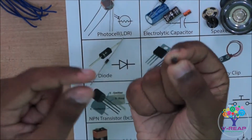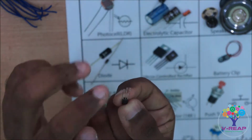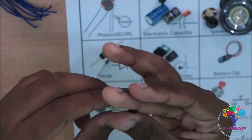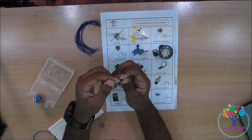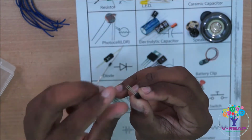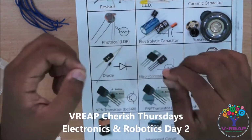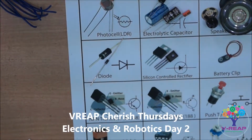The NPN transistor has a characteristic bend on the sides. The side two terminals have a slight bend in them. So let's place the NPN transistor in its place. Coming to the PNP transistor, it has 188 printed on it, and it doesn't have any bends on any of its 3 terminals. So let's place this PNP transistor in its place, and let's continue to the next component.